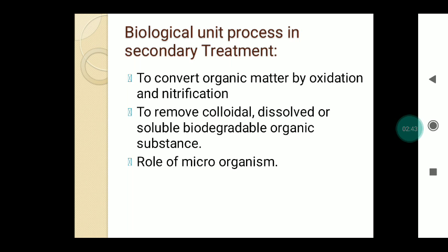The last one is the role of microorganisms. It is very important to decompose or oxidize the organic matter present in the sewage. The bacteria utilize the dissolved oxygen from the sewage for the decomposition of the organic matter. DO is very essential for the respiration of the aerobic organisms. In the biological treatment process, the dissolved oxygen can be supplied through a natural process or by a mechanical process by agitation. To perform this process a favorable environment is needed, and it is provided for the DO for the decomposition of the organic matter.